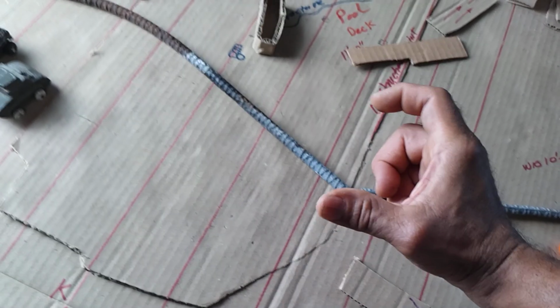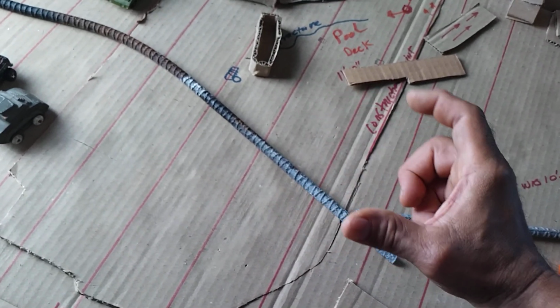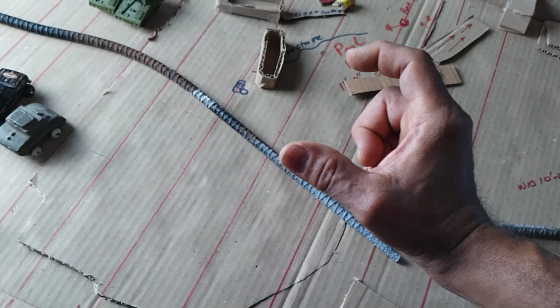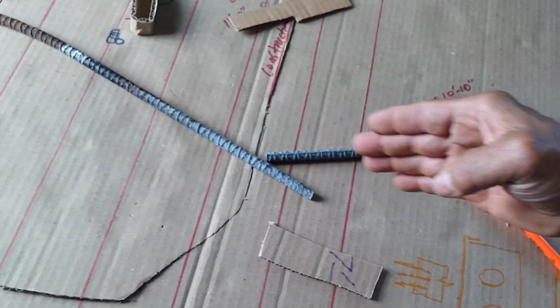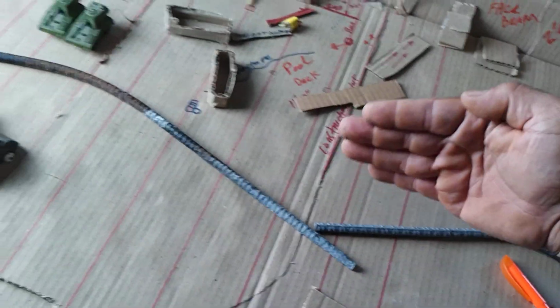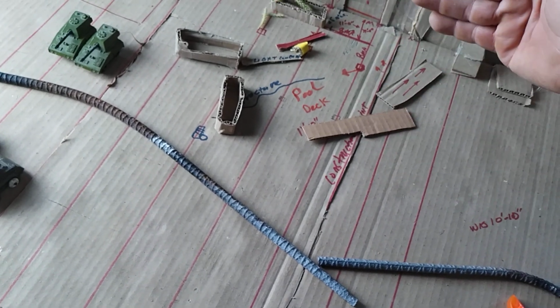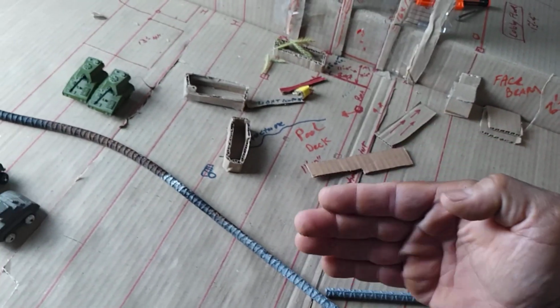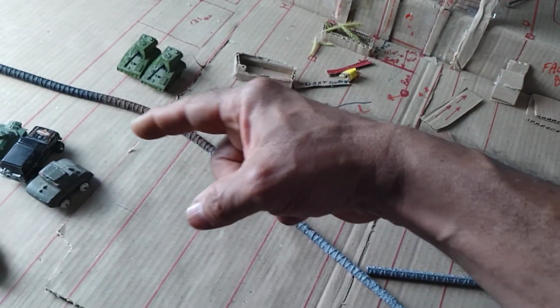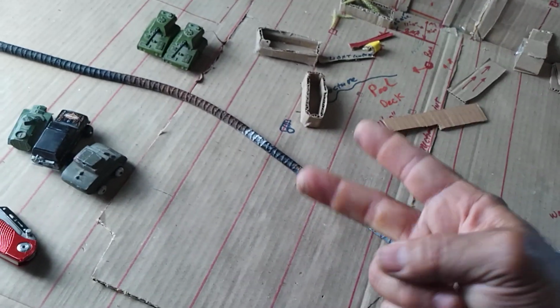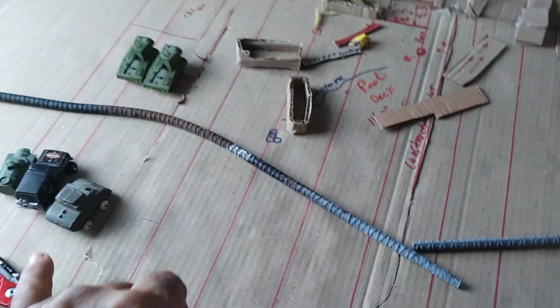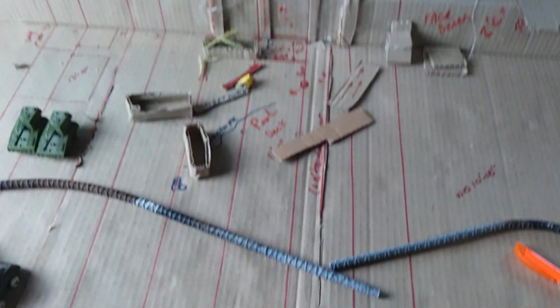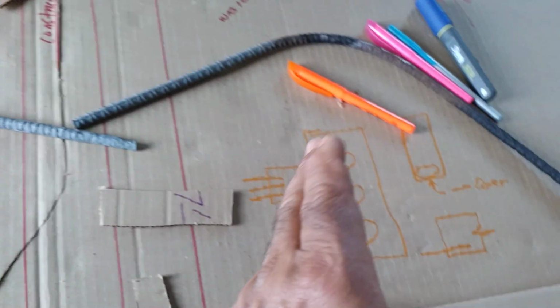It would have meant that extra rebar reinforcement and would have gone down in this capacity, pulling over to the pool, possibly shearing there, but it would have been jointed all the way down like this. That would have slowed up any of that breaking coming across. So now we have another means that could have saved this collapse progressing back to the building. That would have been if this construction joint was done properly.